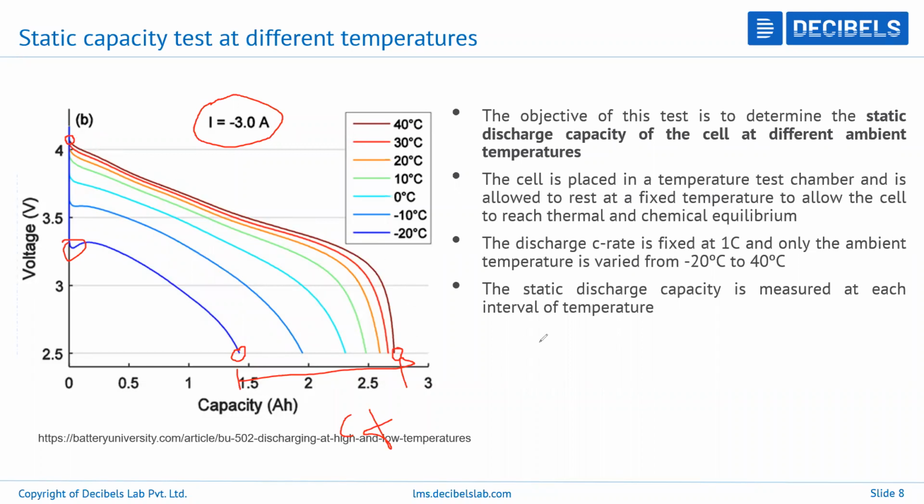One thing which we all know is that lithium ion cells are very famous for something called self ignition or thermal runaway. This phenomenon is pretty dangerous if you expose the cell to higher temperatures, and that can cause your electrolyte to start vaporizing inside. That can cause the cell to catch fire, which is pretty dangerous if you take it to higher temperatures like 60 degrees. Which is why usually for lithium ion cells, 60 degrees is the upper operational limit.